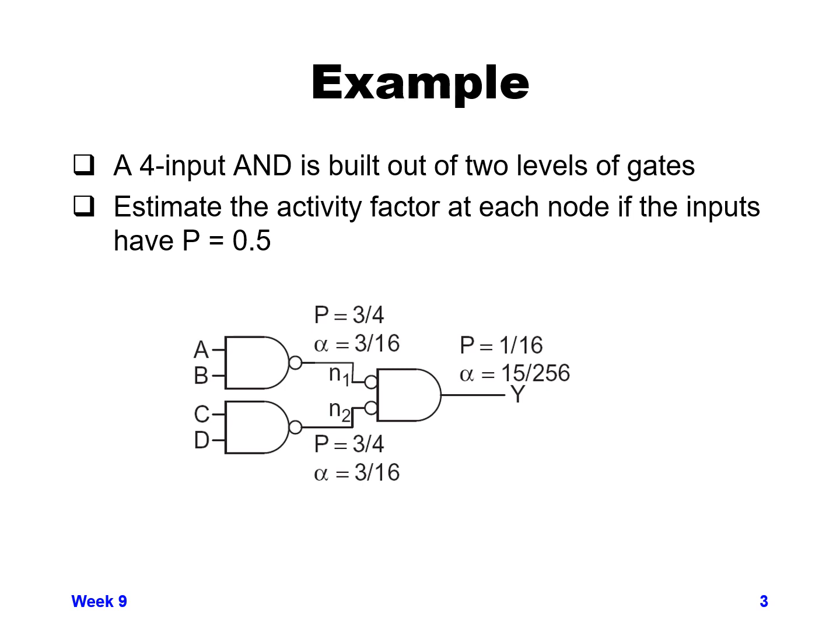So you can see from that, going out of a 4-input AND gate, we get 0.058 approximately. So you can see that depending on the logic you go through, you can start with totally random data, and the activity factor actually gets lower a lot of times as you go through the combinational logic. Exactly what the logic is determines how much lower it gets over multiple logical stages.